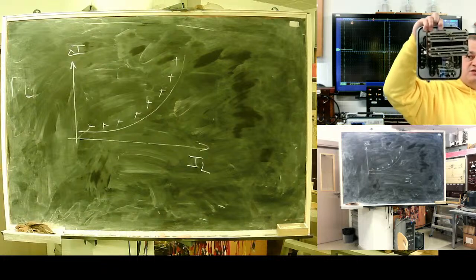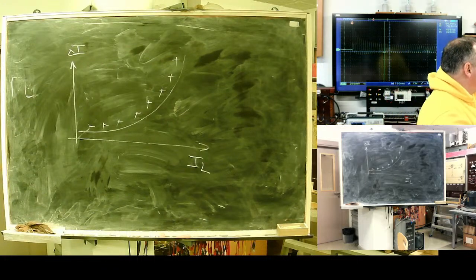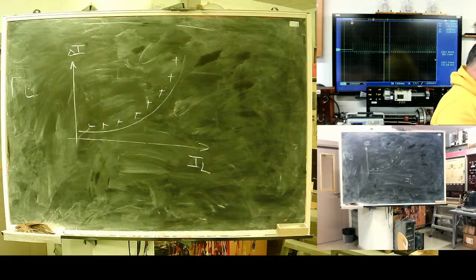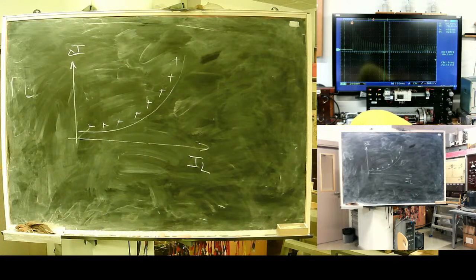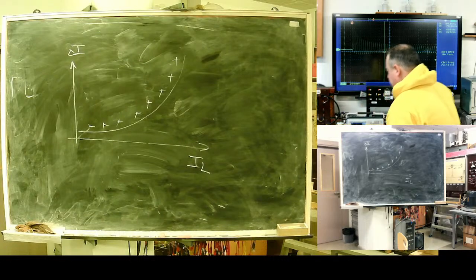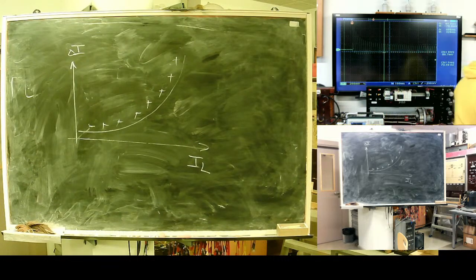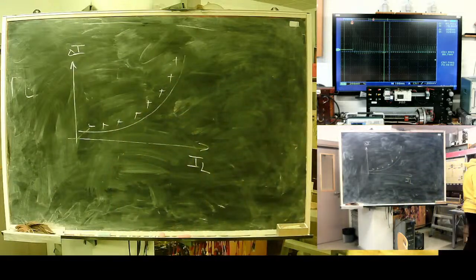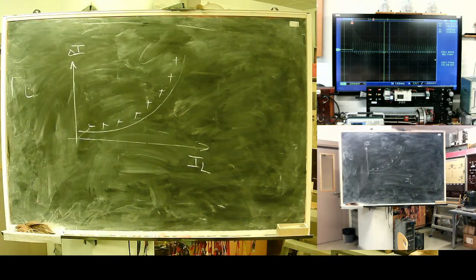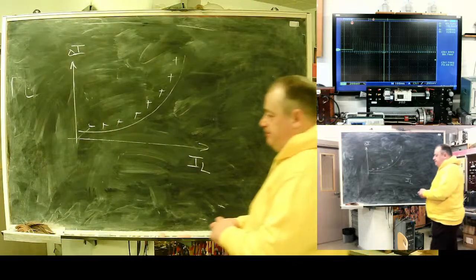Operation characteristic of this one. It's a relay for transformer protection. This one is often used. They are still in operation for transformer protection. Relay with differential current. Trip point dependent on load current.